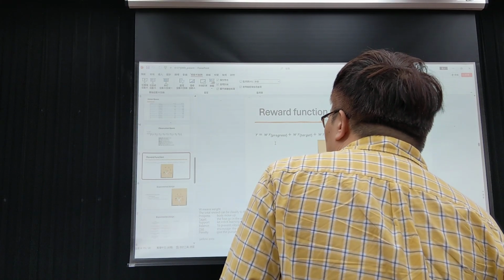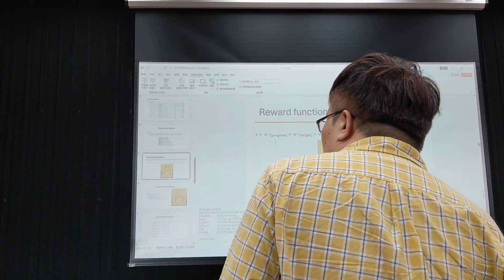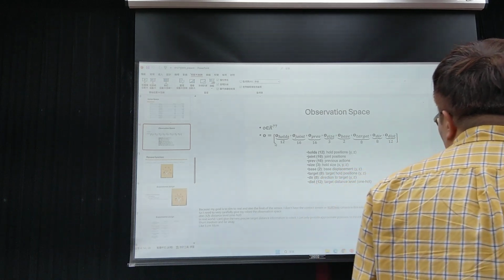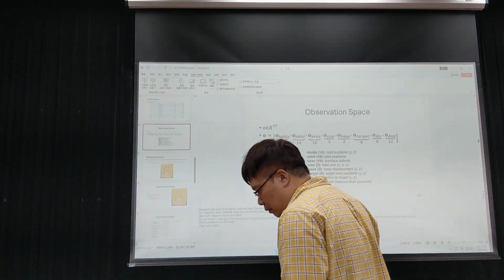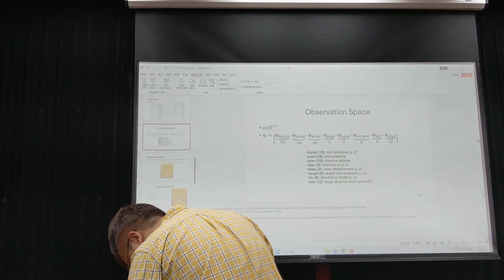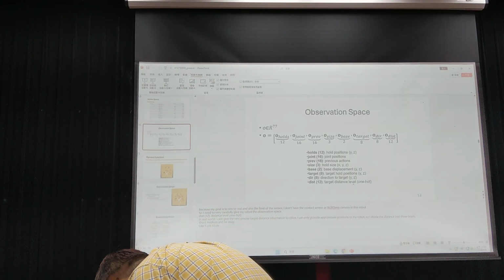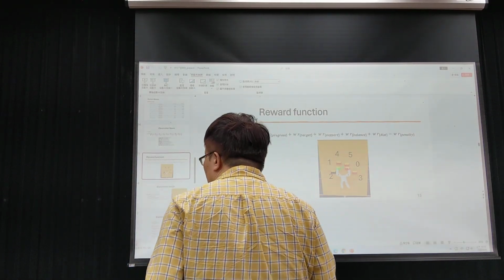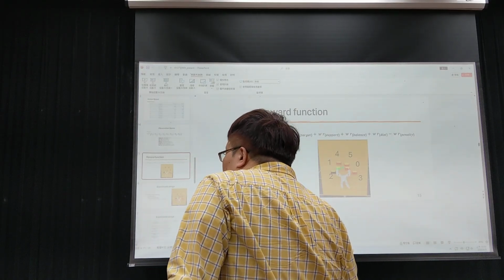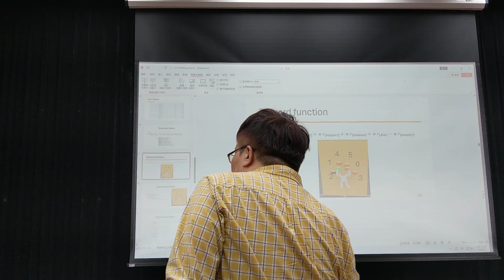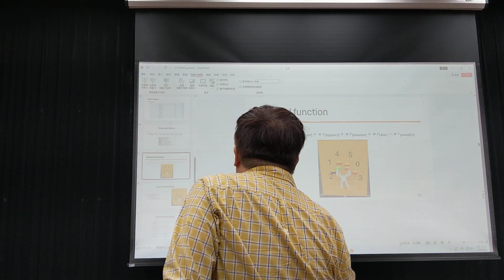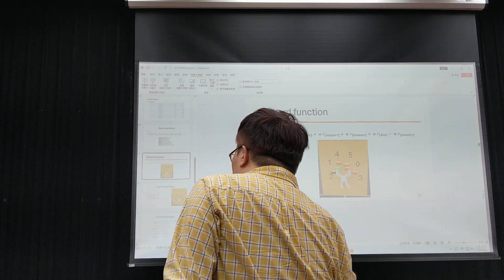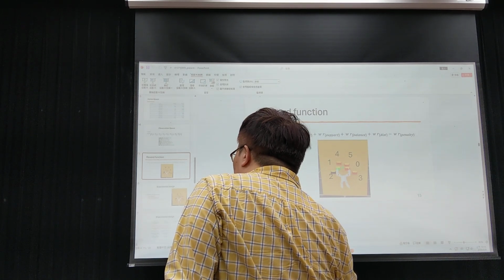And the second, target, is because my robot doesn't have a really precise sensor. Let me show you the observation. Our observation is the last one. The target is tangible. In the real world, I cannot give a very precise distance to the robot, so I divide it into 3 levels: far, medium, and short. And because I only have a camera, the target means he wants to reach it. It will force him to go there and then try to hook on the pole.